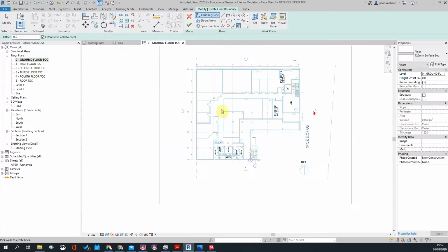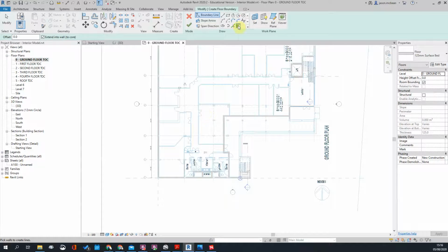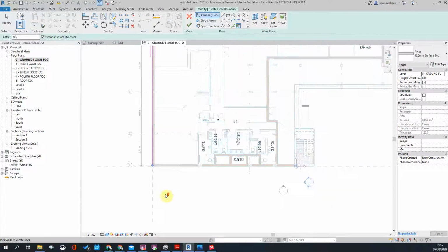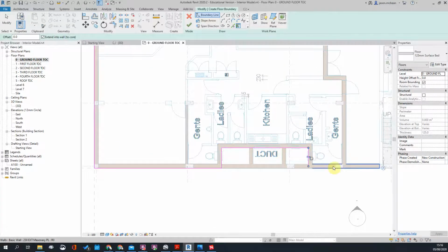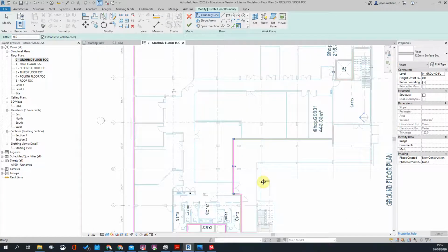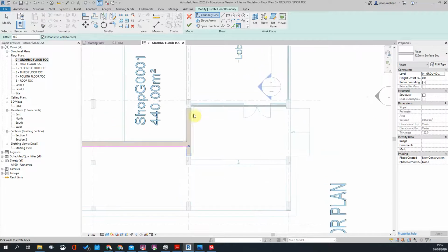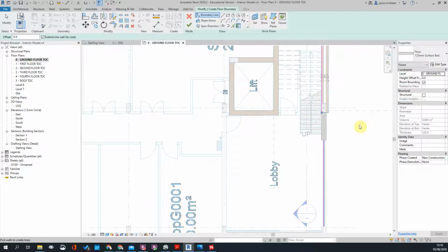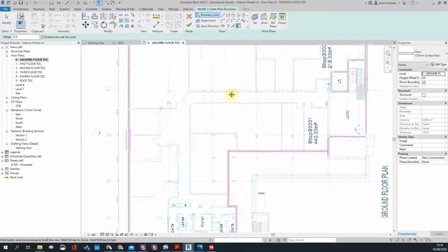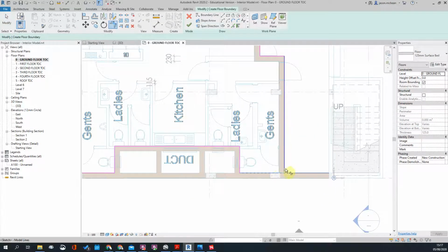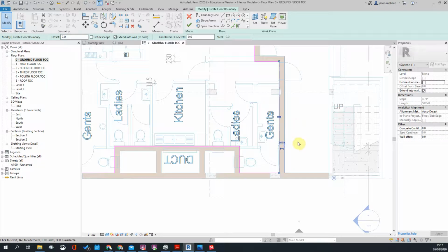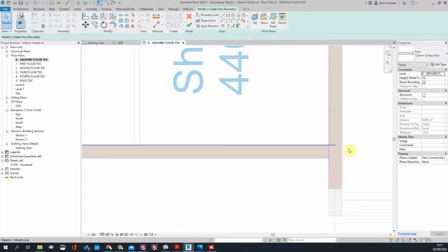So this is going to sit on our ground floor level. What's neat is you can pick walls in this instance. So here I can say it'll pick the line of the walls. So your surface bed will use these types of walls. Okay, but this is still early days. Just remember you need to pick what side of the wall it needs to be. I want this to be all interior walls. That one will switch to the interior side of the wall.